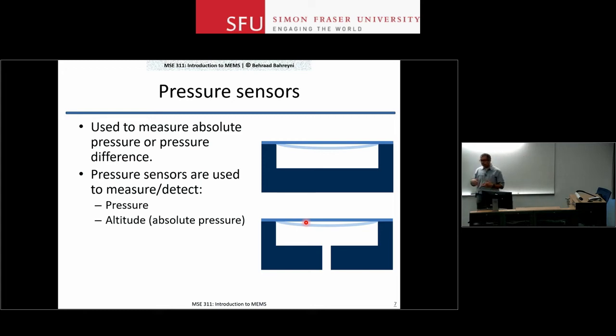And then the modern MEMS pressure sensors that are out there are so sensitive that a half a meter pressure height difference, or maybe even less, a foot height difference, will give you a different reading of pressure. And that's amazing. You can actually easily use it to figure out on which floor of a building you may be without knowing anything else.